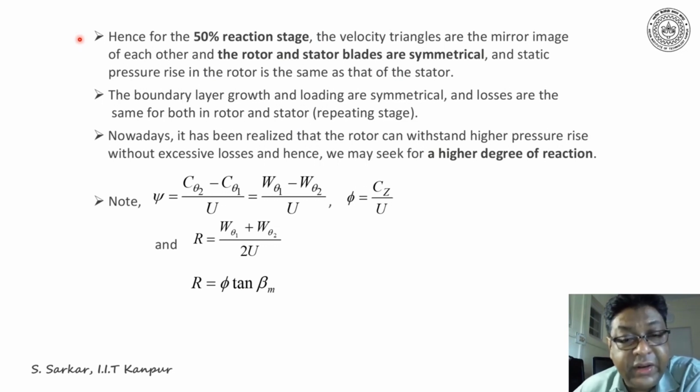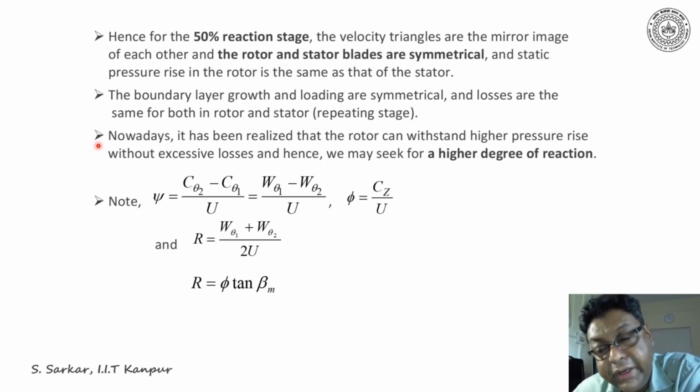The static pressure rise in the rotor is the same as that of the stator. Furthermore, the boundary layer growth, loading are the same and the losses are also the same for both rotor and stator. So thus we are leading to the repeating stage. Nowadays it has been realized that the rotor can withstand higher pressure rise without excessive losses. Hence, we may seek a higher degree of reaction.